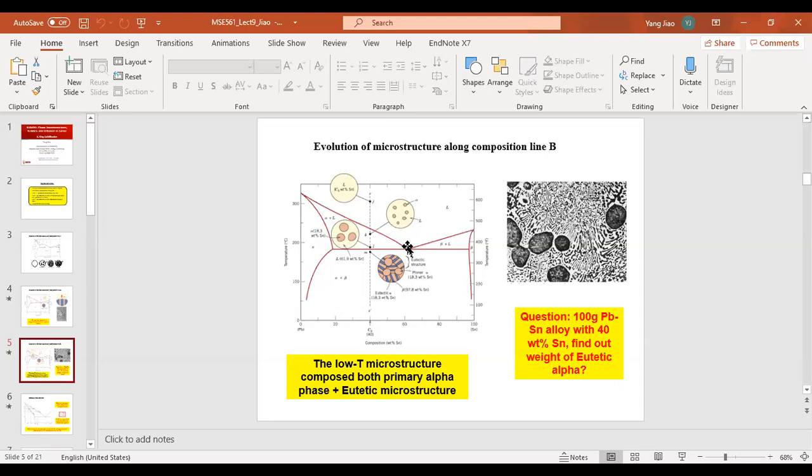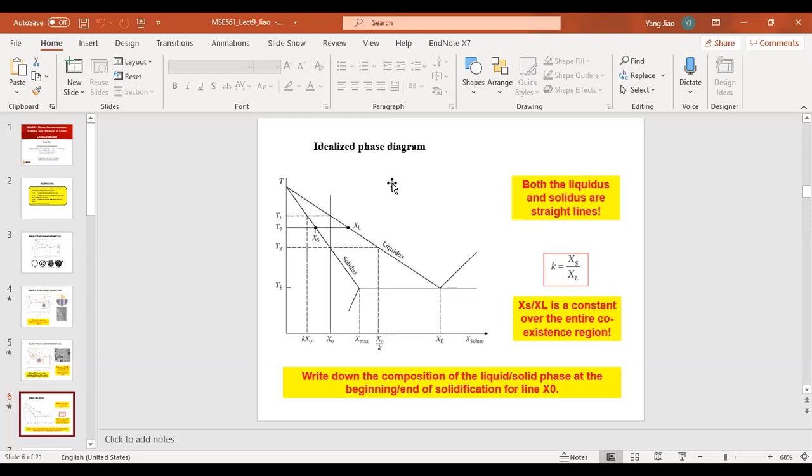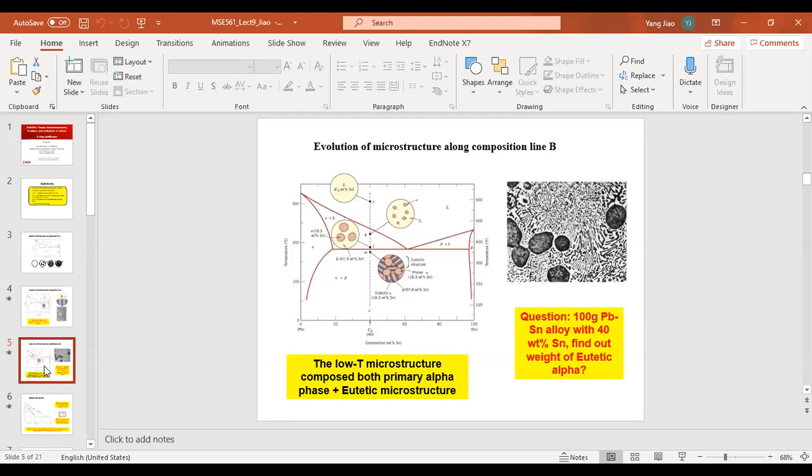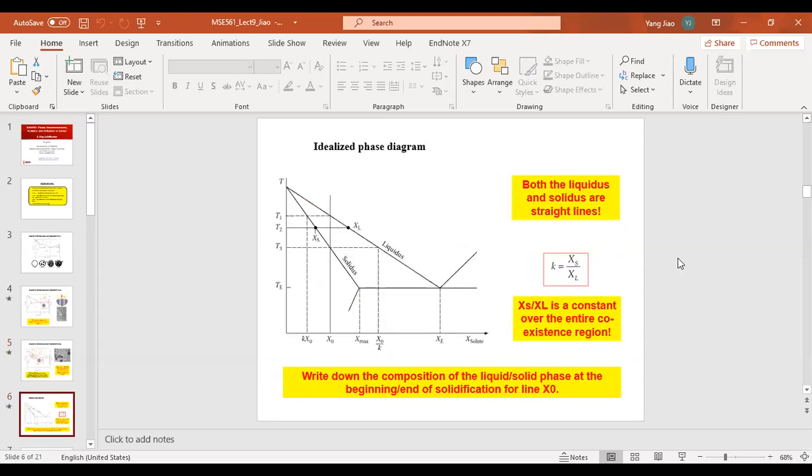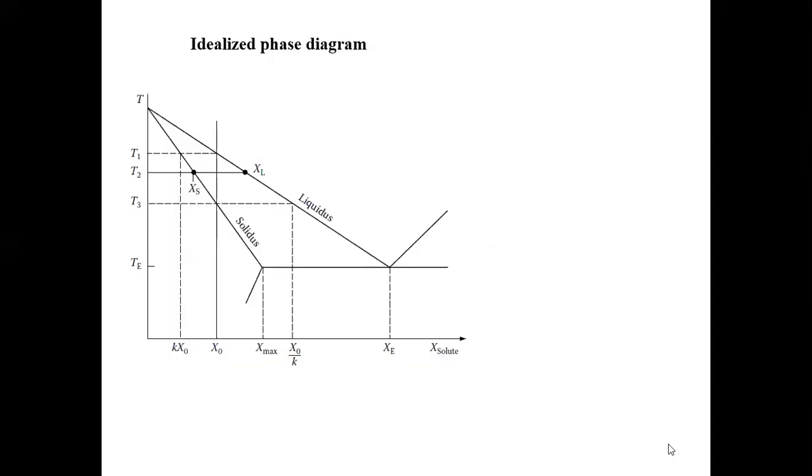Okay, so that's basically our setup. Yes, so you can see that our discussion is mainly based on the phase diagram, right? We focus first on pathway A, where we are interested in the nucleation and growth processes in the alloy. To make our job easier, and this is the juicy part that we discussed in the last lecture, we made an assumption that, at least for the purposes of this class and for the composition we're interested in, which is usually small, we can locally approximate the liquidus and solidus as straight lines.